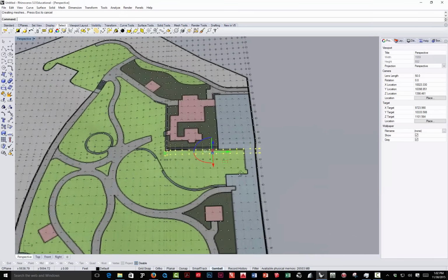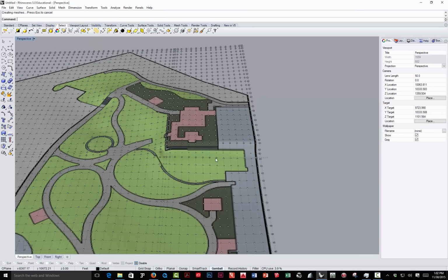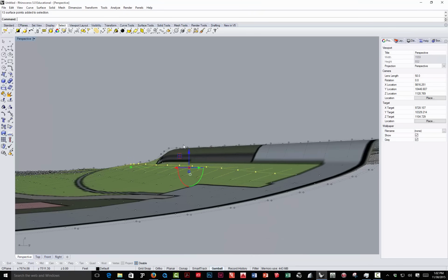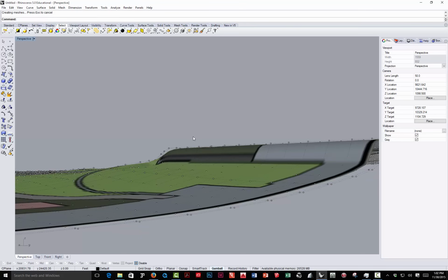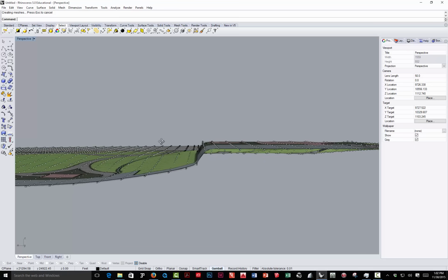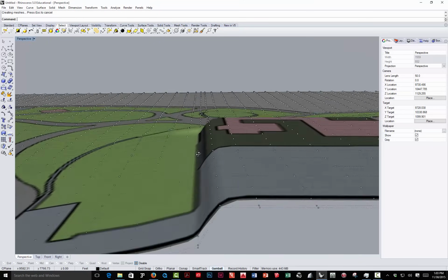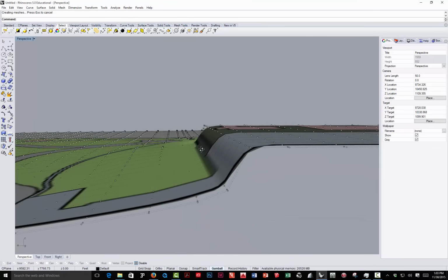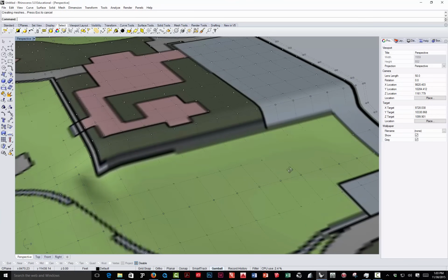And I still have this set right here, which I need to adjust. But again, I can go through here now and grab those and just flow those down a little bit. Okay, so now I've got that landform adjusted. And once I place the wall in there, I'm not sure that's going to be quite within the wall, but if that's the case, I will select this group of control points and move them into the wall. But I'll wait till I drop the wall in.